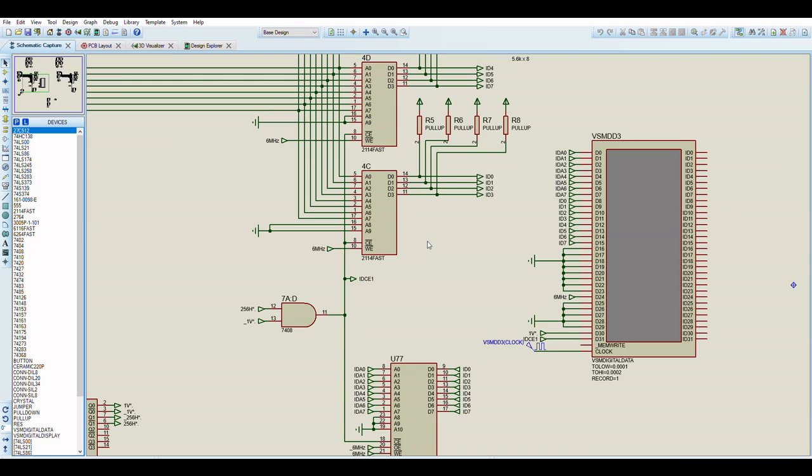then I may have to have odd and even pixels inside the scan to give enough time for the sprite rendering to finish its read or write cycle with these RAMs. Might have to do that, which would make things a lot more complicated again. The whole raster line schedule is actually documented fully in the Readme file.